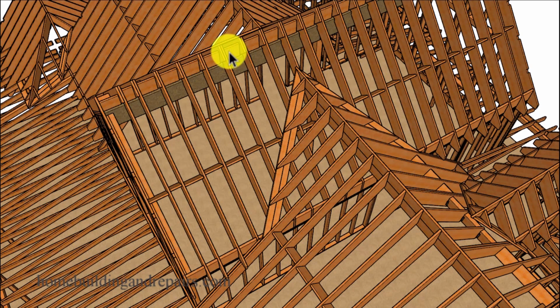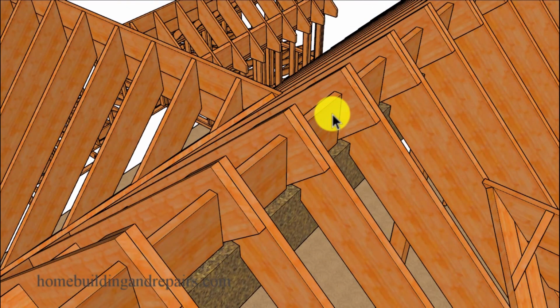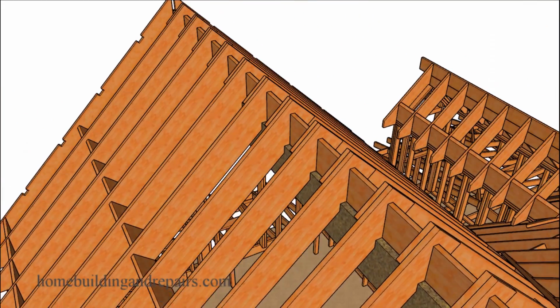And I went ahead and left these blocks a little lower, but you're probably going to need perimeter nailing. These blocks will need to go all the way up to the ridge. However, I have seen them lowered before like this when installing ridge vents, something that will allow the air to circulate out of the attic or into the attic through a ventilated ridge that might be made out of metal. I don't think I've ever seen them made out of plastic.